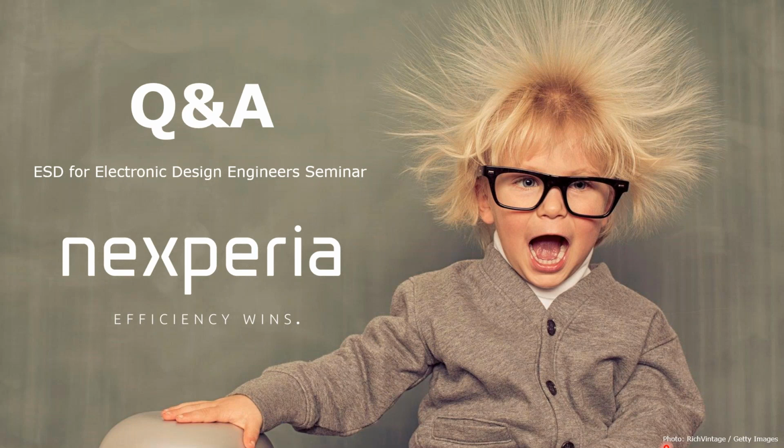You have to characterize the system extremely accurately. Usually use TLP to also characterize the nonlinear effects of the passives and stuff like this. And it allows you to understand what actually happens and where the current is flowing and how and when the ESD protection devices are triggering. And this is actually required when tuning high-speed ICs with suitable ESD protection devices.